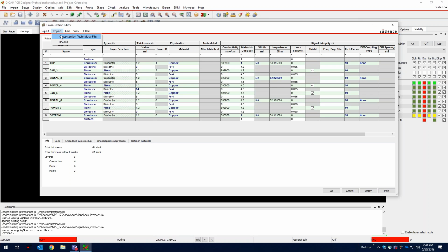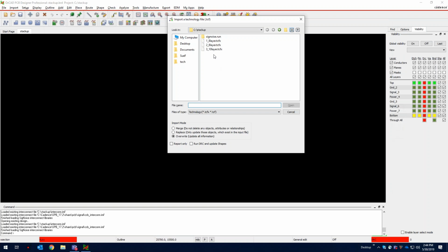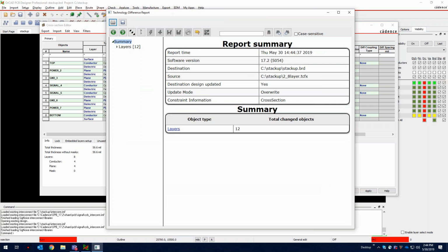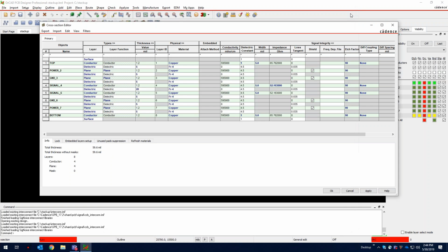Now, an even better 8-layer Stackup might have 2 power and ground plane layers to help with your power delivery, and these plane layers can be tightly coupled. The high-speed signal layers are at the center of the board. Notice that both of these Stackups have been symmetrical around the center line.